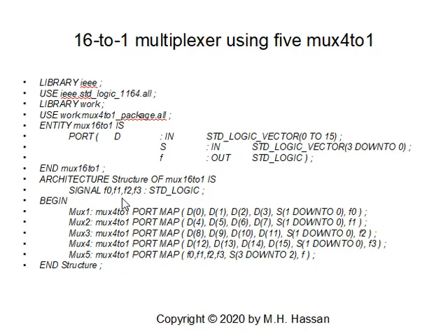We have to define them, otherwise we'll get an error, because they are not outputs and not inputs, so we don't define them in the port statement, but they have to be defined in the architecture. So signal F0, F1, F2, F3 in standard logic.